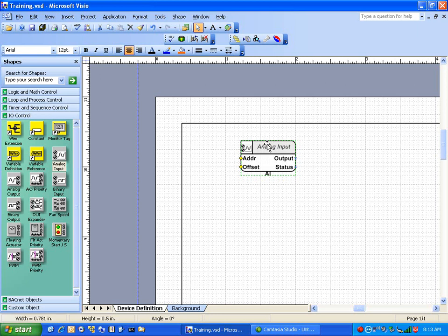Or else you find yourself trying to set up a simple graphic screen and you're having to pull out your drawings just to figure out what AI1 is. And back in the days, we used to label a lot of jobs AI1, AI2 as our inputs, and I'd like to steer people away from that because this is the base, this is the grounds.